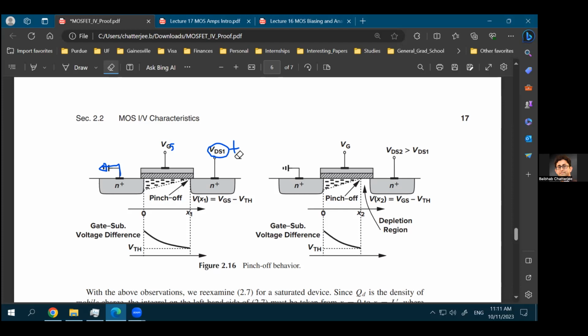The concept of threshold voltage is that you need to cross the depletion barrier, the built-in potential barrier, so that you can expect a current flow through the device. That's the concept of threshold voltage. You need to reduce the depletion region to almost zero, so that you can get a continuous current flow. But the depletion region always exists, and if you apply the reverse bias, the depletion region becomes wider and wider.